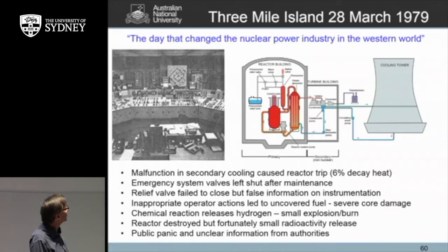The other problem was this PORV, pilot operated relief valve. It got stuck open, but the indicator on the control panel said it was closed. So this led to the operators doing the wrong things. They weren't very well trained anyway to deal with emergency situations, but they were fed false information. So this led to uncovered fuel, which led to severe core damage.